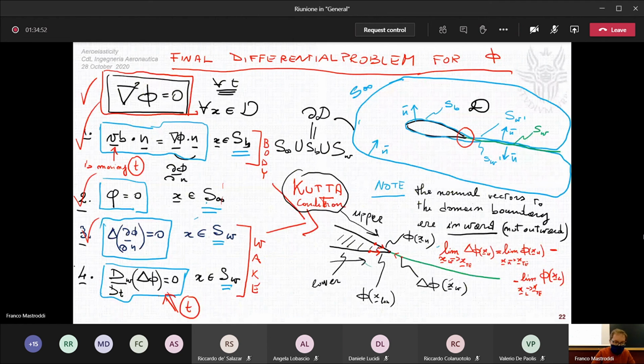And let me do a check mark now. Okay? I have used the Kutta condition because I have moved delta phi on the body to the wake, and fourth boundary condition, I'm assuming that this wake, this continuity delta phi, can be convected on the wake surface by means of the defined wake velocity as average up and down.